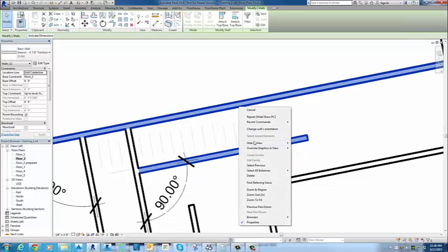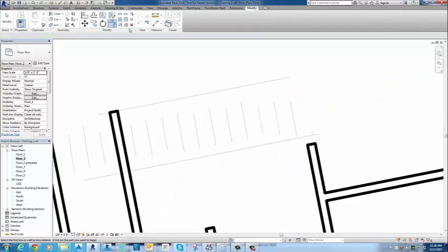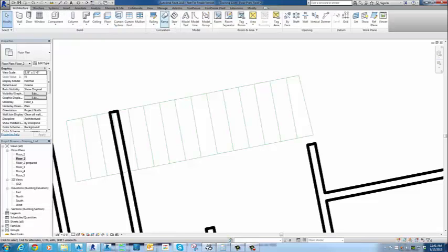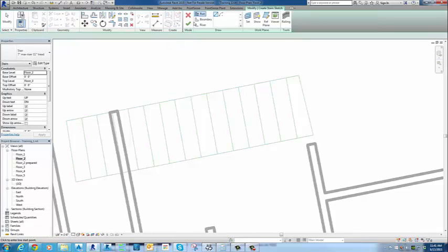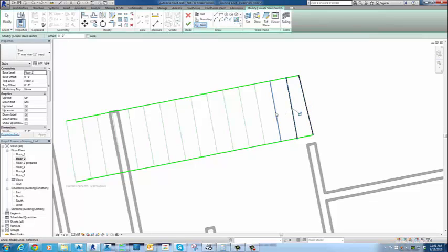So here's our line work, and at this point we just need to trim it up a little bit to get it prepared. So I'll turn off these walls so I can see a little bit better. And those are the horizontal lines that I sent over, and now I can just trim them up to the stairs command, and we're going to do a stair by sketch. And really we just choose the boundary lines first, click those, and then we go through and click the risers.